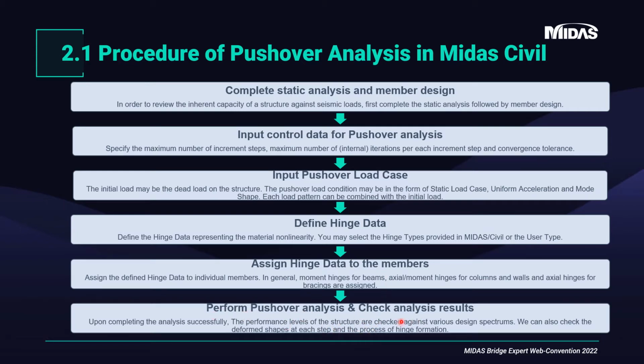And after that, we can check the analysis results graphically, and we can also generate the chord rotation and all those tables from our result tables of pushover analysis. So we can check the performance levels of the structure against various design spectrums. We can check the deformed shapes at each step and the sequential formation of the plastic hinges.